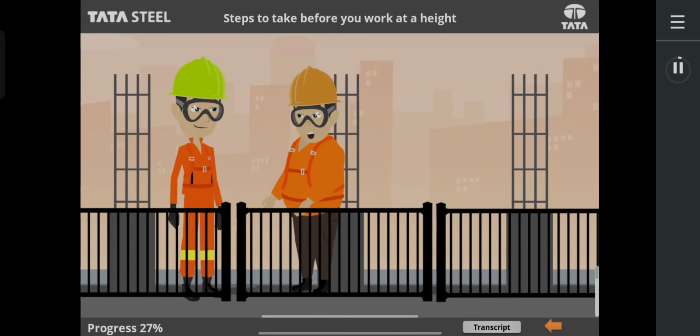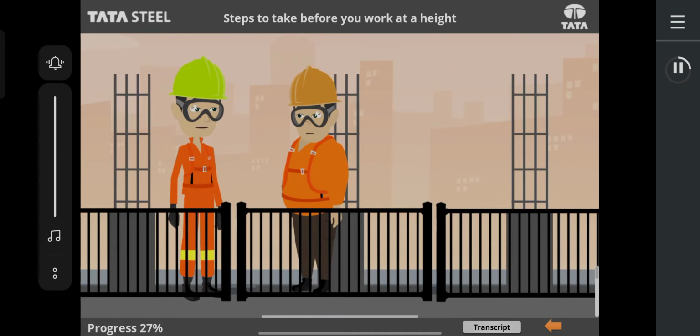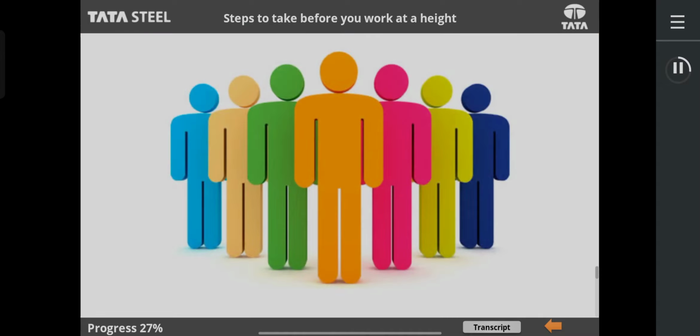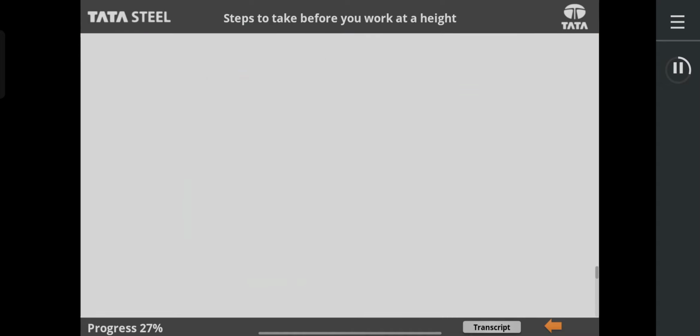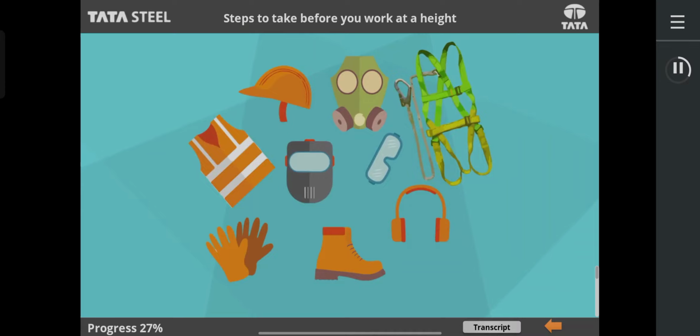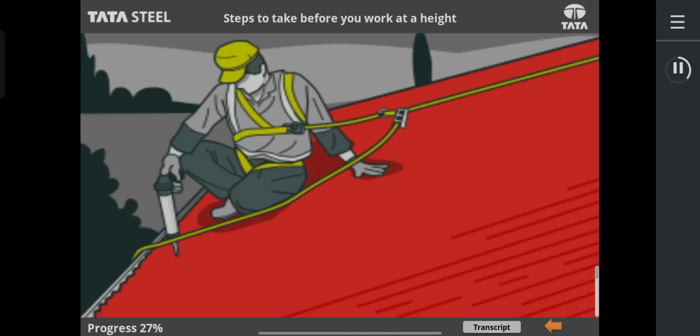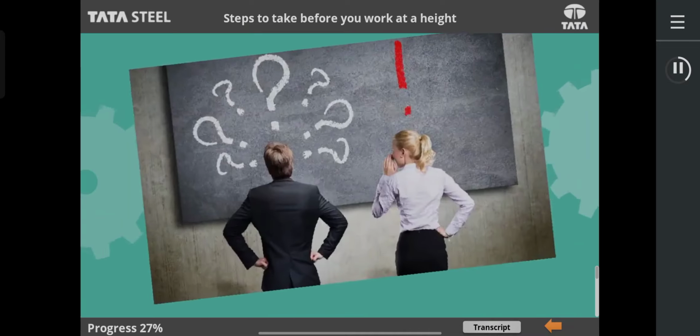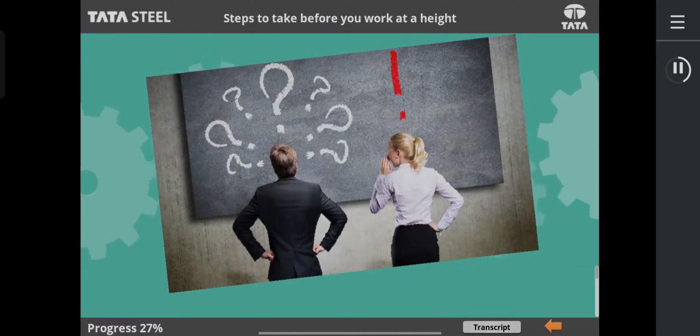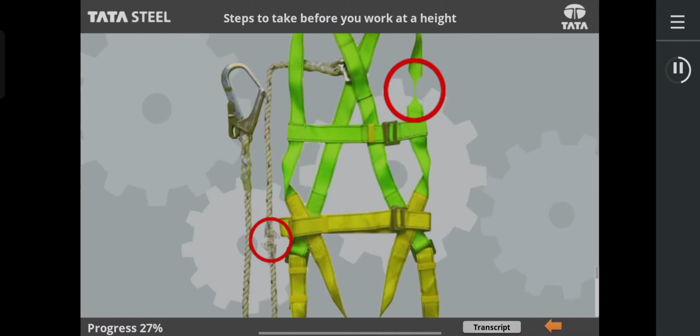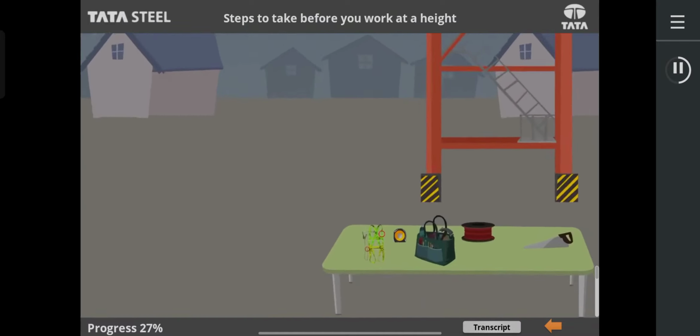In the accident involving Irwin, it was the worker's mistake not to wear the belt, isn't it? It was a mistake, but the mistake is not his alone. Whenever there is a job that requires work at a height, there should be a complete assessment of the personnel, equipment, and work surface. In this case, the worker was not trained and there was a faulty belt harness which should not have been there.